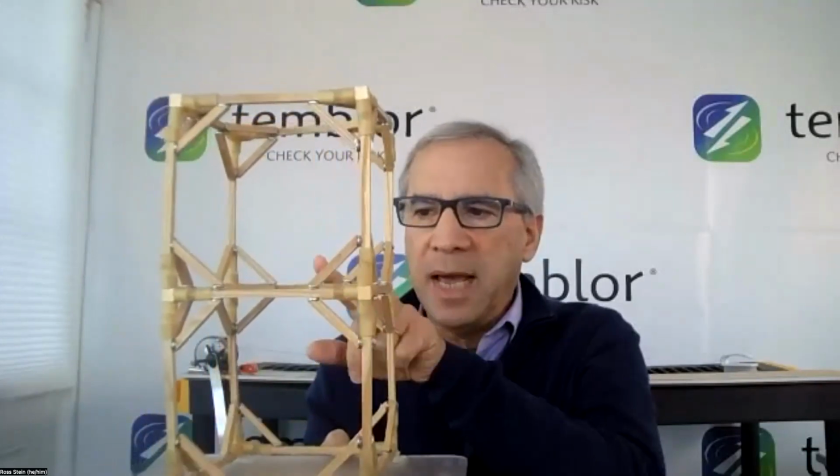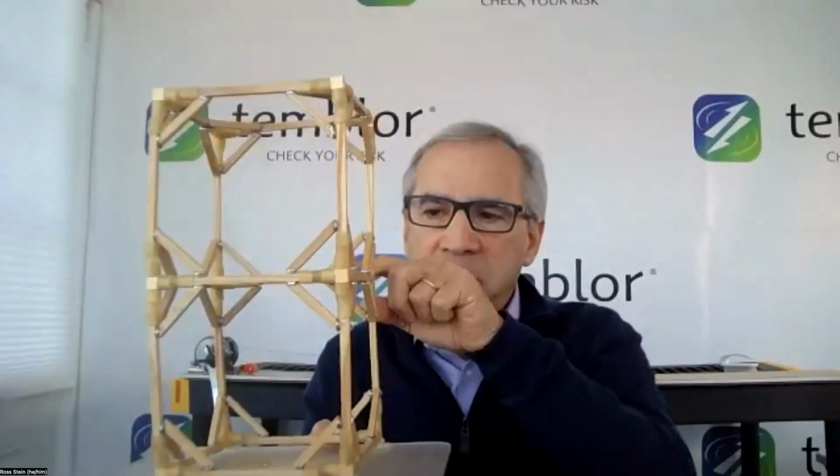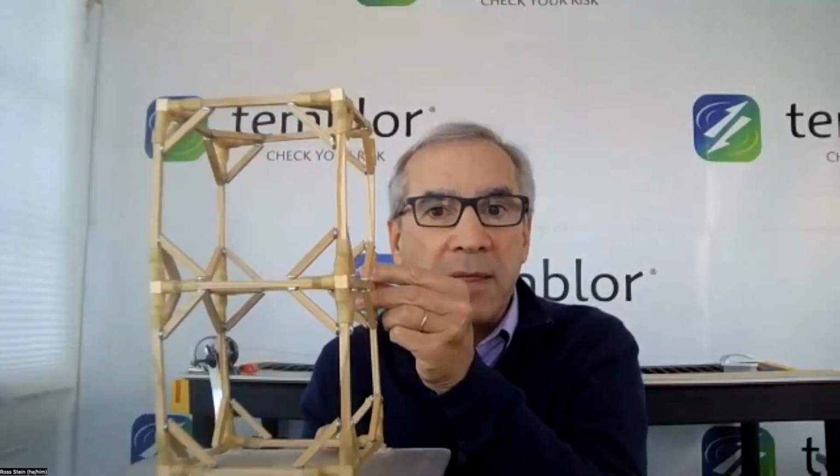And in a reinforced concrete building, which is the typical building style in Turkey and pretty much around the world, particularly for tall buildings, we obviously don't have these corner triangles. What happens is there's rebar, steel reinforcing rods inside the concrete columns and beams, and that splays outward in the corners and is wrapped and is strengthened more in the corner than anywhere else.